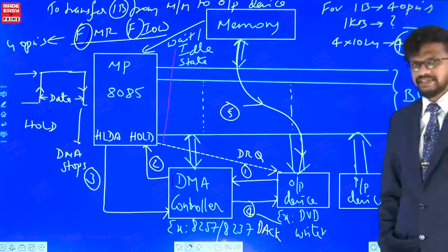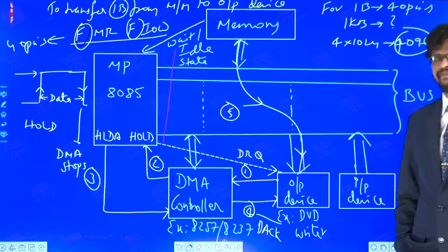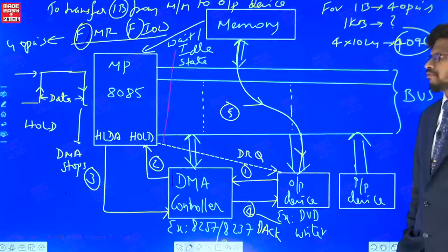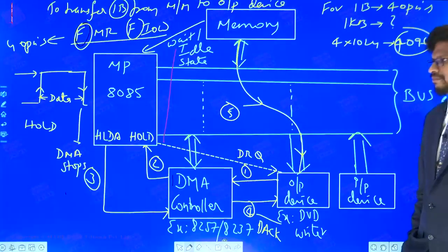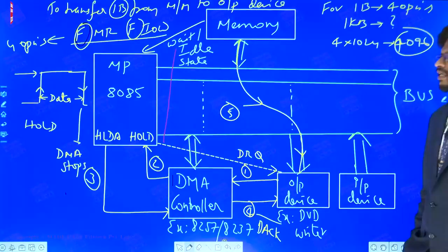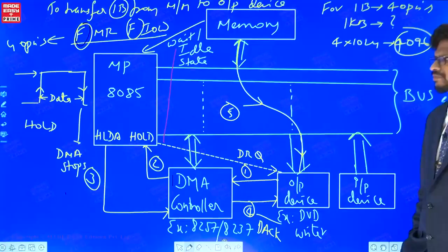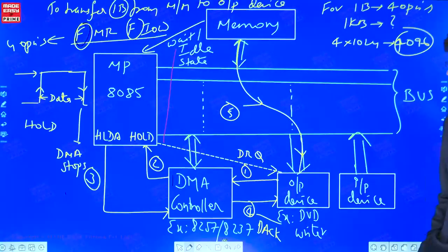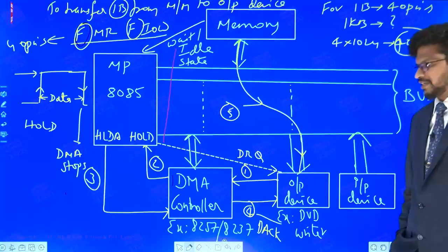When the processor receives hold signal which is high active, the processor completes the current operation and responds with HLDA, hold acknowledgement.